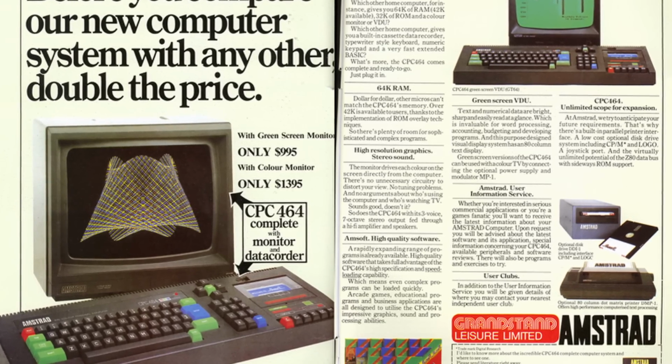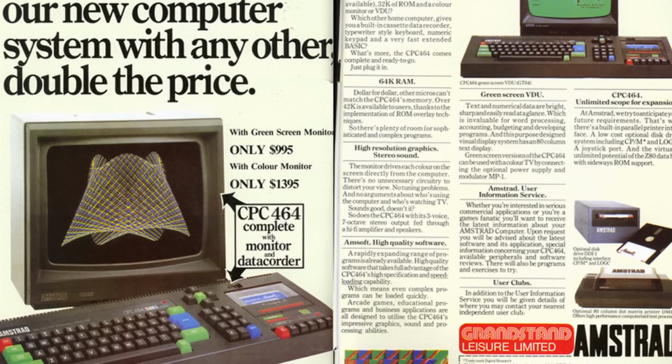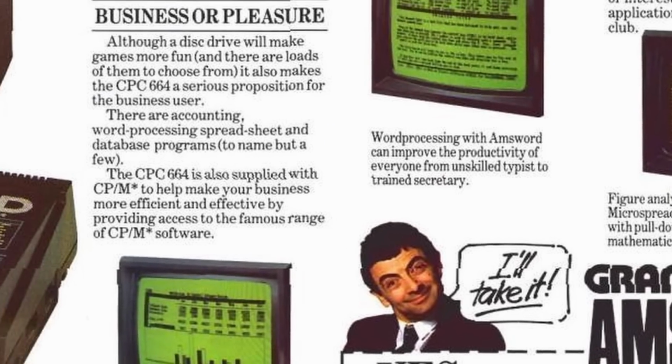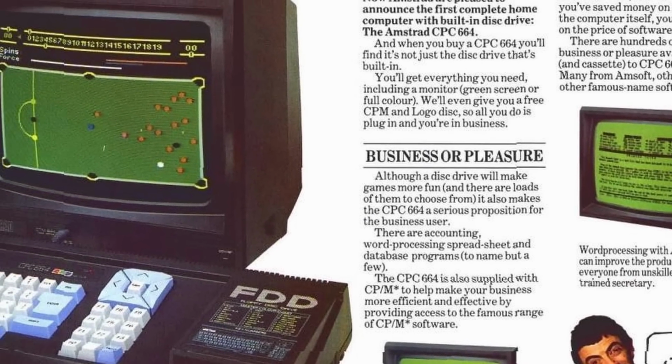One of the most distinctive features of the Amstrad CPC 464 was its 64 KB of RAM, which could be expanded up to 512 KB with memory expansions. Additionally, graphics offered a resolution of 160 by 200 pixels and a palette of 27 colors to choose from. It uses a General Instruments audio chip, which provides 3 channels. The output is mono with a small built-in speaker and the possibility of stereo output through a headphone jack.